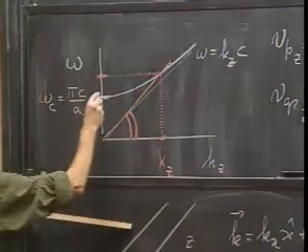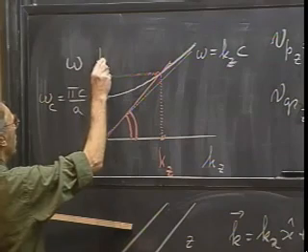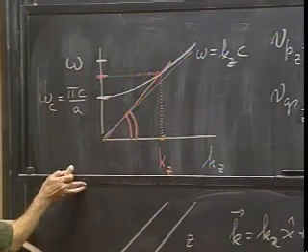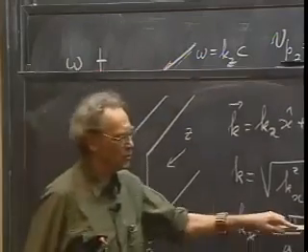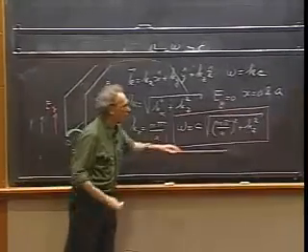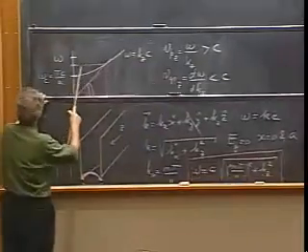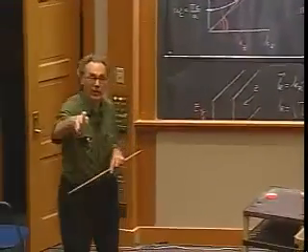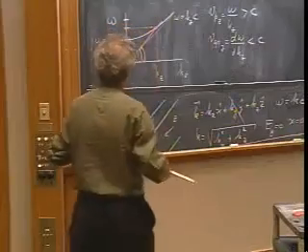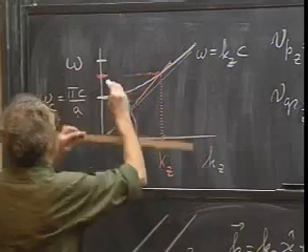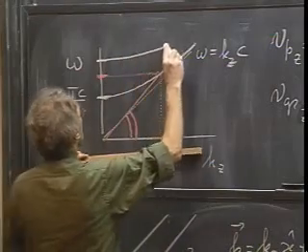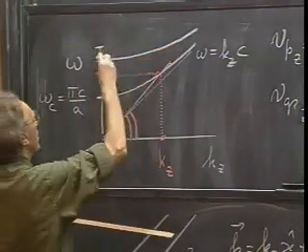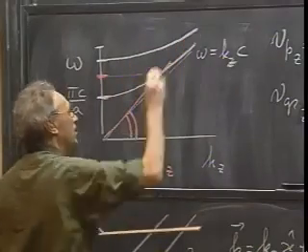If you go to very high frequencies, there is another cutoff frequency, which is twice this number, because that is when m equals 2 and kz becomes 0. Then, of course, there are two different ways that you can propagate radiation in the z direction, because now you have here the line, and if your omega is high enough, then you get an intersection with this line, and you get an intersection with that line.